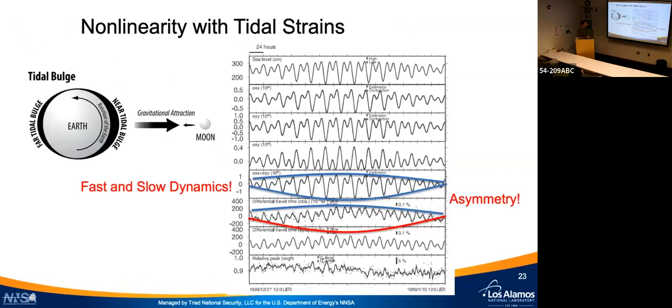And this is what it looked like, a representative 14-day period. What we're looking at here is the strain. They had a strain meter there, and this is EXY. This one right here is the areal strain. This is the sea level. So this is related not to the solid Earth tides, but to the ocean tides, because they were sitting right next to the ocean, and this is with the ocean level going up and down. What do you mean by areal strain? The horizontal 2D tensor. Oh. Yeah. And what you can see here is the strain.